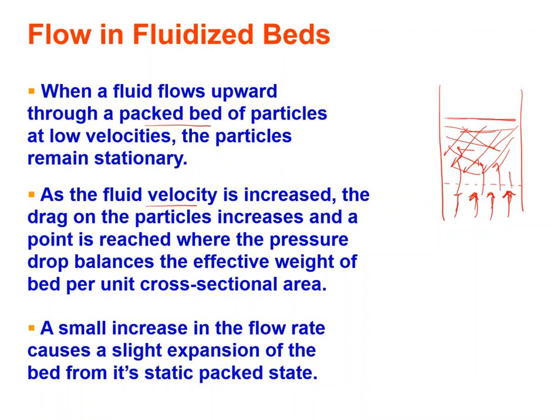A small increase in the flow rate causes a slight expansion of the bed from its static packed state. If this was the original volume, now the particles will go up a little bit and the bed will expand. So I no longer have the static packed state. I'm going to the fluidized state, where the particles are moving. They are not stationary.